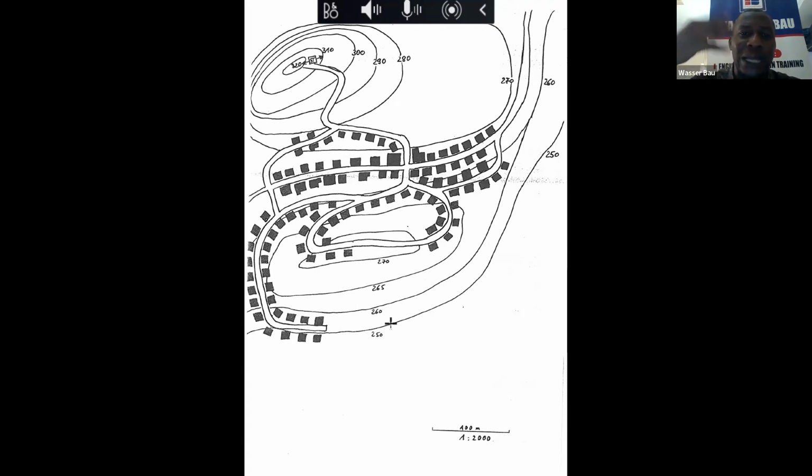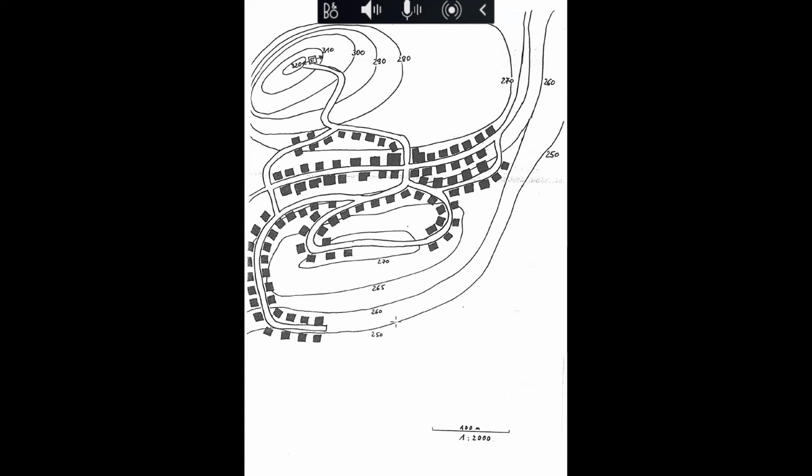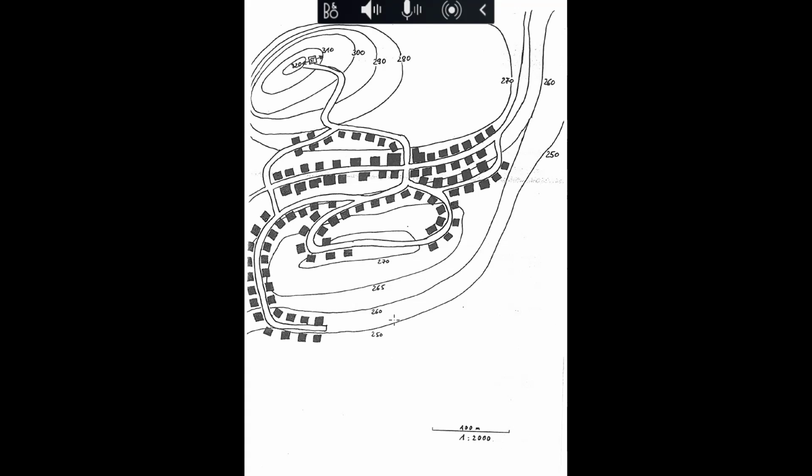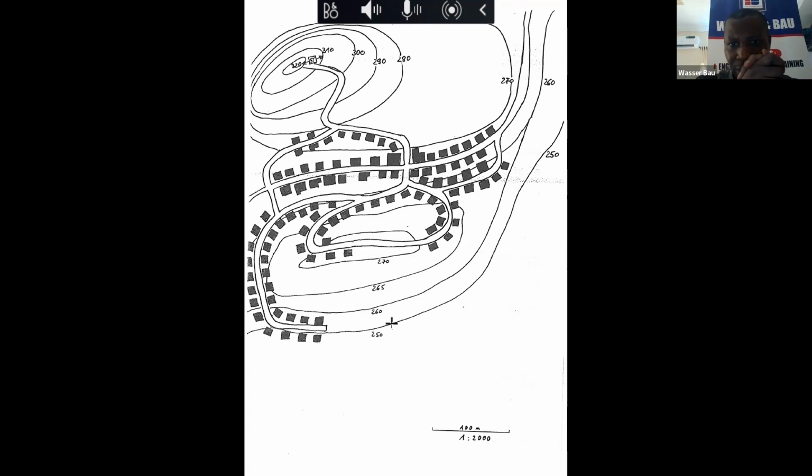But you and I know it cannot be up to 6 bars; it might be around 5 bars. We dedicate 5 or 10% for losses due to momentum change, losses due to the pipe network, and losses due to valves. The losses for valves, fittings, and bends, just incorporate into the pipe losses, or frictional losses.